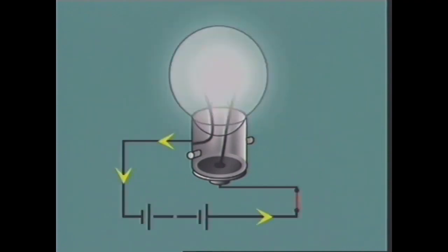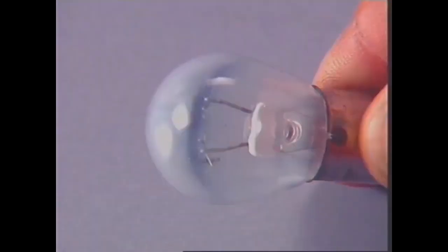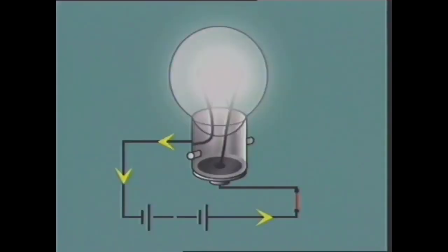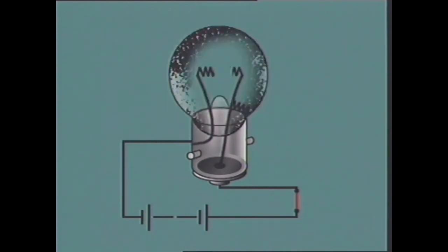Passing a current through the filament raises its temperature to a white heat and causes it to give off an incandescent light. Removing air from the glass envelope prevents oxidation of the filament when it is in operation and increases the filament life. In high wattage bulbs, particles of tungsten can boil off the filament, even though the air is removed, and eventually cause filament failure.